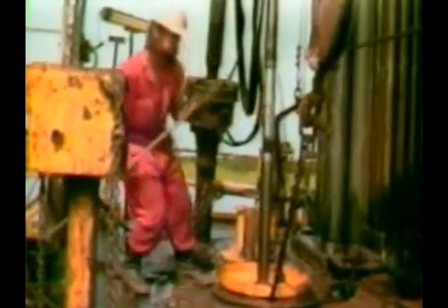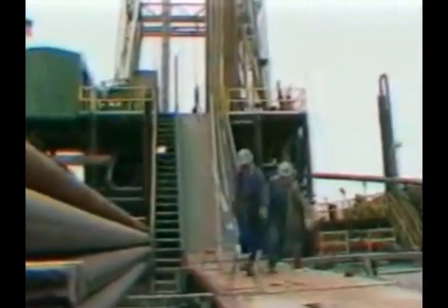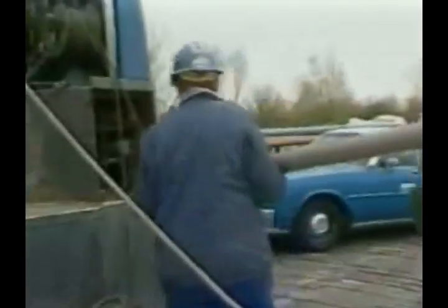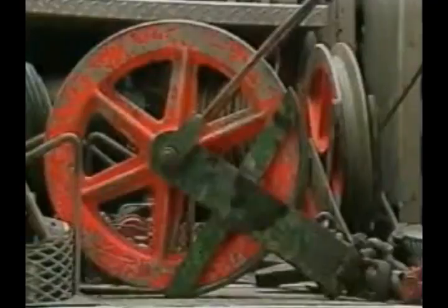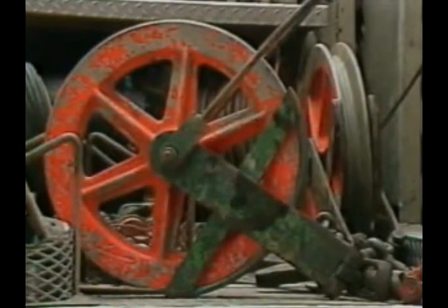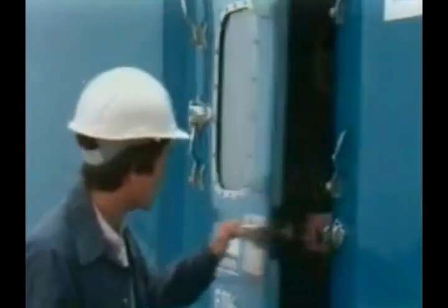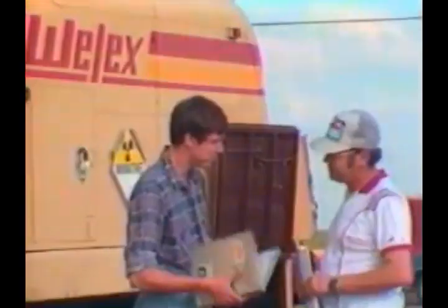Upon completion of the last logging or sampling run, rigging down proceeds in a manner similar to the reverse of rigging up. Any radioactive sources are removed from their devices. Logging tools are lowered back onto the catwalk, cleaned up, broken down, and racked for transportation back to the field office. Sheave wheels and accessory items are detached and stored in the truck, and the cable system is secured. Field prints are made for the oil company representative.